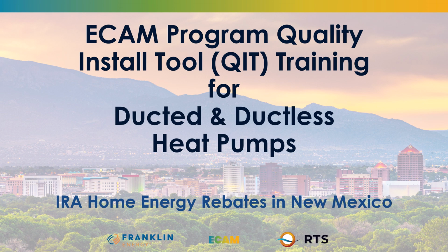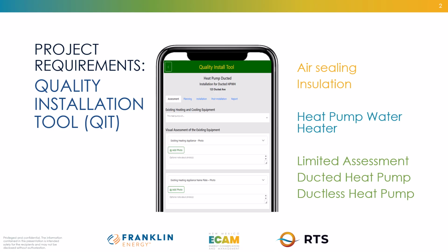This short webinar will cover detailed instructions for using DOE's Quality Install Tool, or QIT, for ducted and ductless heat pumps. Several qualifying improvements will require use of the PNNL Quality Install Tool. All qualifying appliances must be Energy Star.